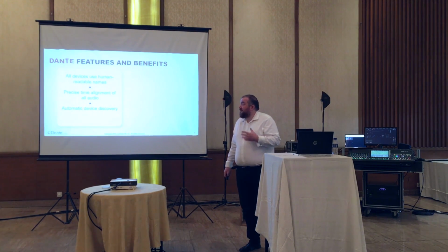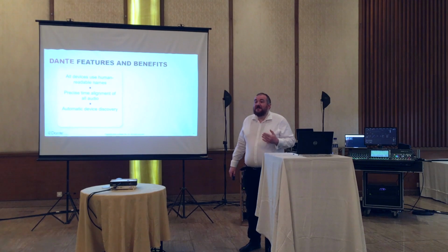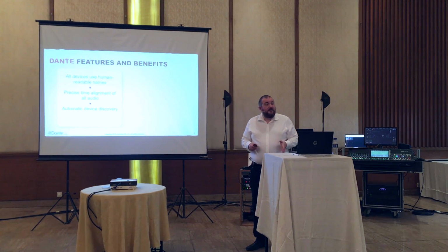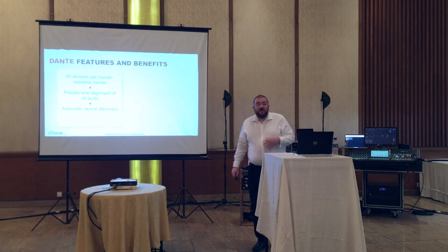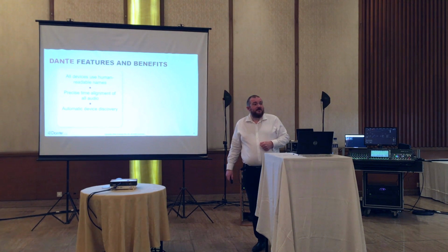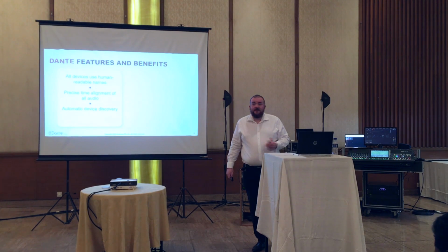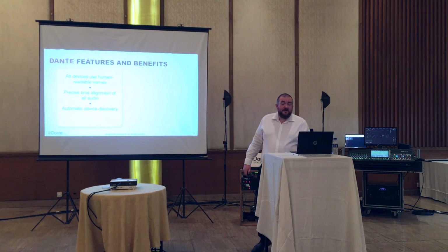We precisely time align all of the audio. So everything in a Dante network is synchronous to within plus or minus 1 microsecond. So just to put that in context, we were talking about samples earlier. At 48 kilohertz, one sample is about 21 microseconds. So all of the devices are synchronous to within about a 21st of a sample. So yes, when people say sample accurate, it's not just sample accurate, it's phase accurate as well. So yeah, really, really tight synchronization.